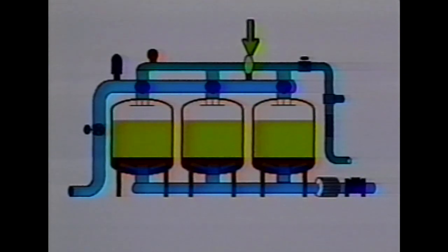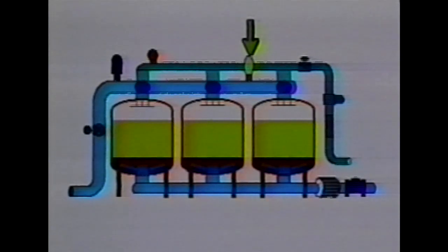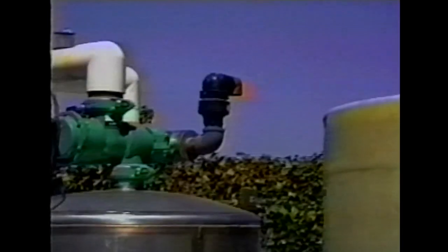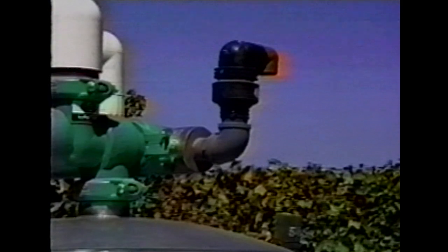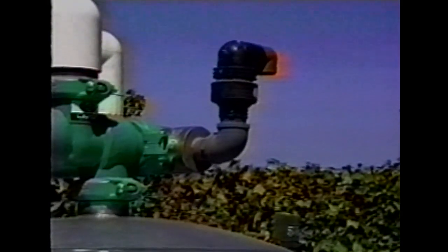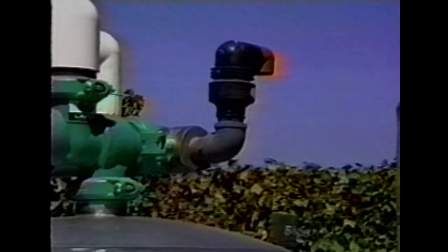A combination air vent, which includes continuous air release capabilities with vacuum relief, should be located at the downstream end of the supply manifold. It helps evacuate air from the piping and tanks when the system is being filled up with water and during operation.